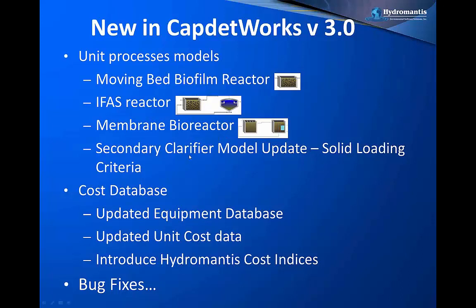Also, we have made some small modifications to our secondary clarifier model, in which we have included another criterion, solid loading. Earlier, the design criteria was just overflow rate, but we also included the solid loading criteria in the revised version of the secondary clarifier model.